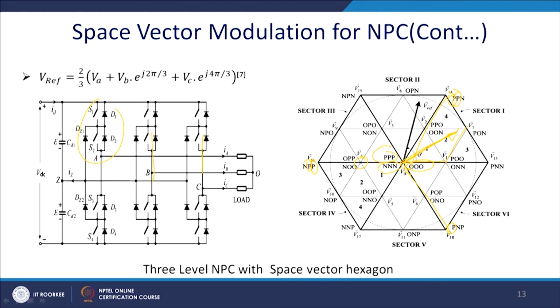And what we require to do, since we can think of this voltage, is to shift the origin here. When you shift this origin here and take this hexagon, you will find that this can be treated as a 2 level inverter, and the same calculations you have done for the 2 level inverter are valid. The same way for this leg also.